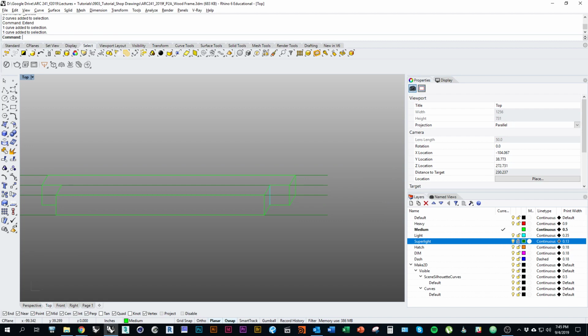And then what I got to do is make sure that the whole thing is the right length. So I could also draw a line just as a reference point. Start right there. The uprights should all be 18 inches, so I'll type in 18, hold shift and click to draw it straight.